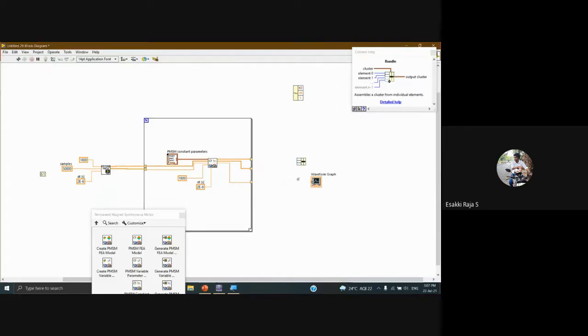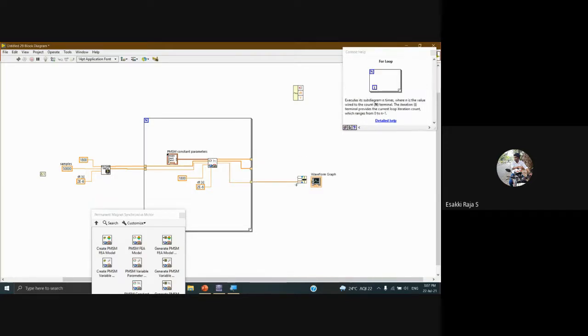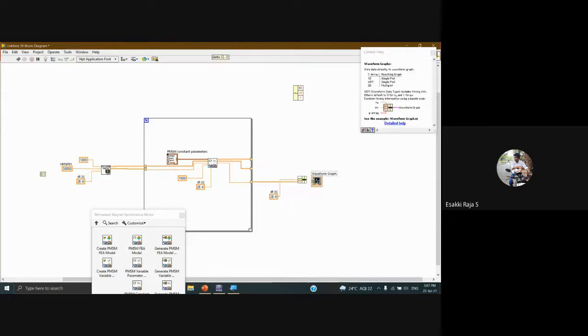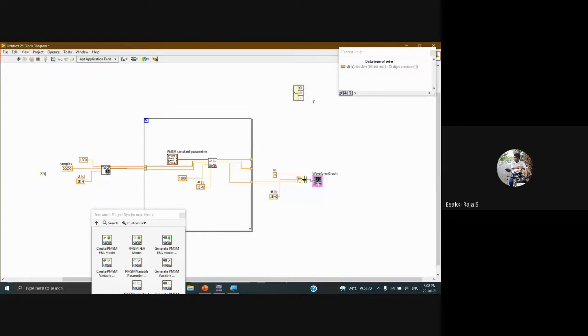So what I'm going to do is, instead of passing this directly, I'll pass this information into the last one, that is y. Then dt, this is the dt value, I can place it over here and connect. And time, I can make this 0 and pass. So this is t0, dt and y. The same way we have to do for every function. I'll just make a copy of it.